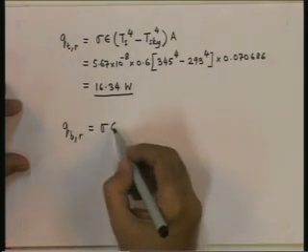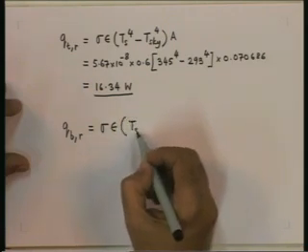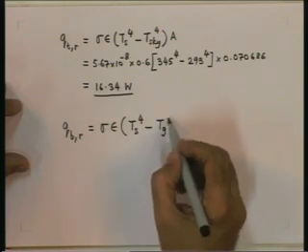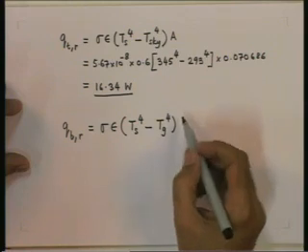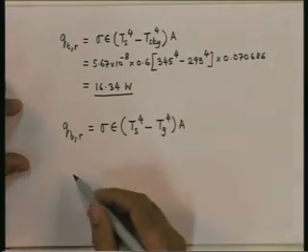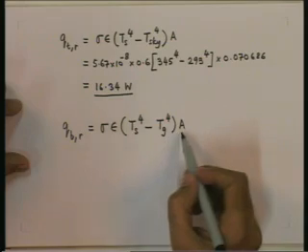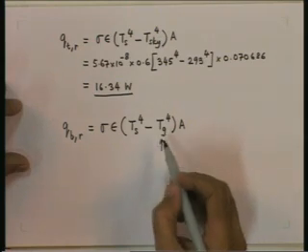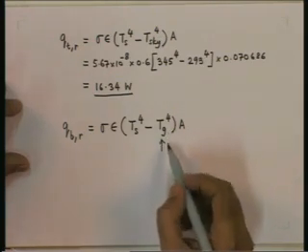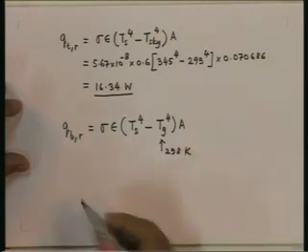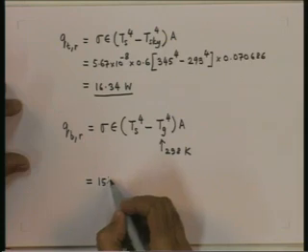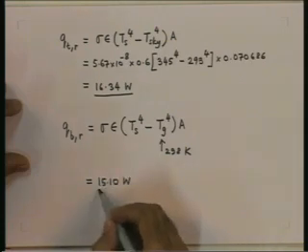Similarly, let us calculate the heat loss from the bottom by radiation. This will again be sigma epsilon, but now T surface raised to 4 minus T ground raised to 4, multiplied by area. Now between this expression and the earlier expression, the only difference is T ground is 25 degrees C, which is 298 Kelvin, and if you substitute that, you will get this to be 15.10 watt.